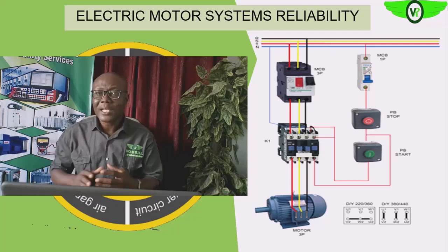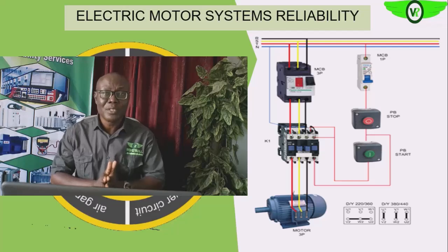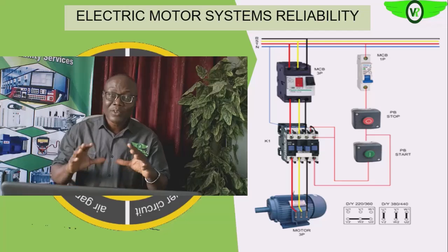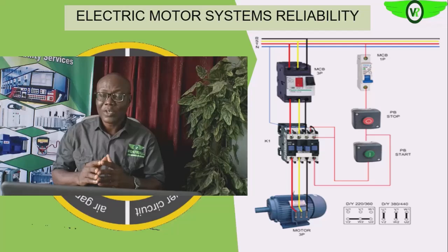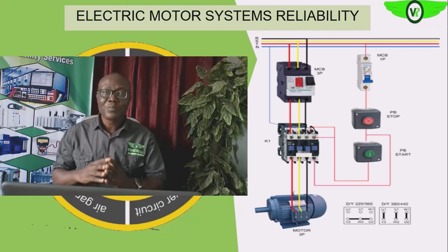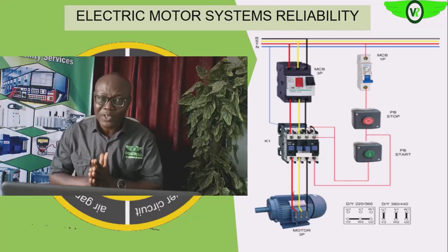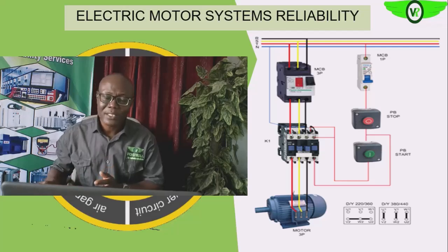Okay, and then their phase difference, like we identified earlier, must also be 120 electrical degrees, since we have deposited those coils on the stator at those separations of 120 electrical degrees. And then we also expect that input power to be at a particular frequency. Are we getting it?